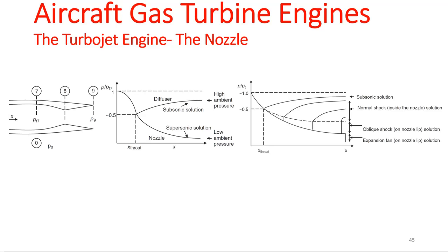No. Where is 0.5? That's one of the confusions I didn't want. That's pressure inside the nozzle, right? Pressure as a function of x. So the nozzle pressure ratio is PT7 compared to the ambient pressure, right? They have the same solution for the choking condition at the throat, but this 0.5 doesn't refer to NPR, right?